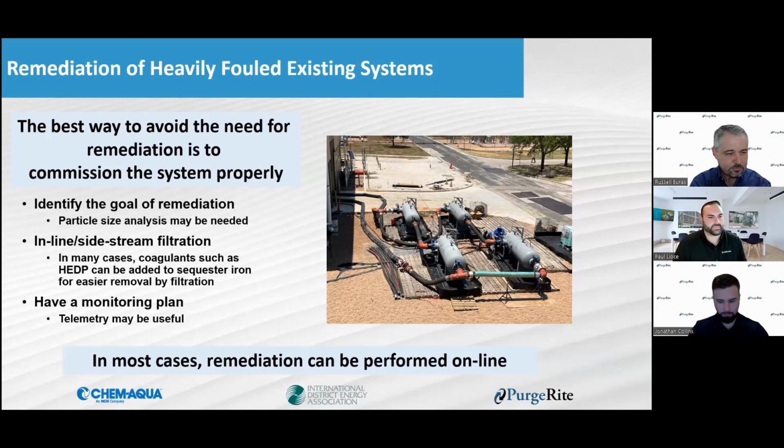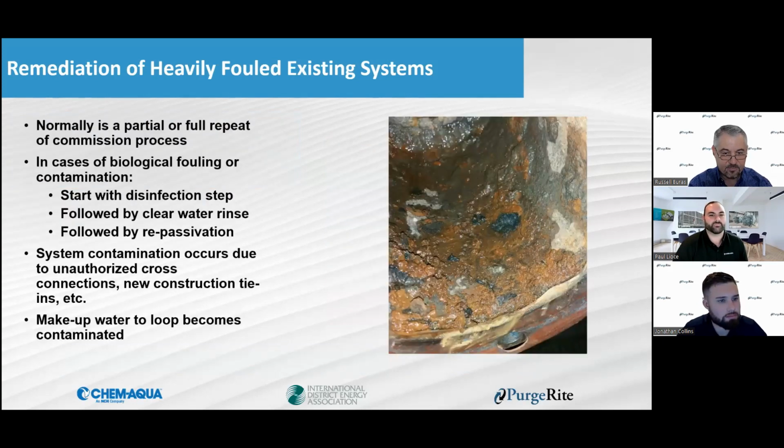Yeah, most definitely. That is a great point, Russ. If you have 8 to 10 ppm of iron in there, from an analytical standpoint we do a particle study analysis, a PSA, and we find that a majority of your particulates on the iron side fall within the 1 to 2 micron size frame. But Russ says, hey, I've got a 5 micron filter out there. So we really wouldn't be doing much good as far as removing it. You would be removing a lot of other particulates in that system, but the main goal of getting that iron down wouldn't be achieved.